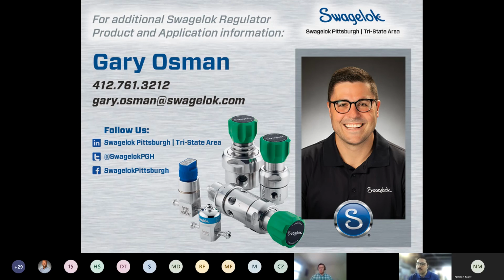Here we got a question. A customer uses a regulator for vaporizing and they get Joule-Thomson effect, and we need to change the regulator regularly. This is a heated line. Should they be looking at potentially a differential regulator? If it's Joule-Thomson related, a good solution may be also looking at two stages. Especially if the line's already heated, gases pick up energy really fast. Even just spreading that pressure drop over two units can be really helpful in combating Joule-Thomson, because the reality is you can't get away from Joule-Thomson.